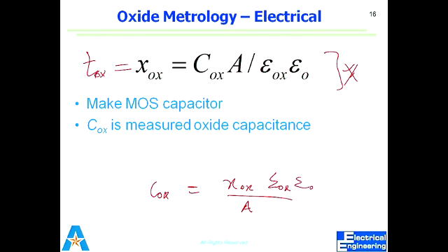We will measure two different sizes, and we will see that the capacitance measurement is different for this capacitor and for that capacitor. So when you measure C oxide, this is what we will measure in the last lab. You know about T oxide because in the first experiment you will be measuring the thickness of the oxide. So when you know the oxide thickness, you can calculate C oxide as well, right? You can calculate your oxide capacitance if you know the thickness of the oxide.